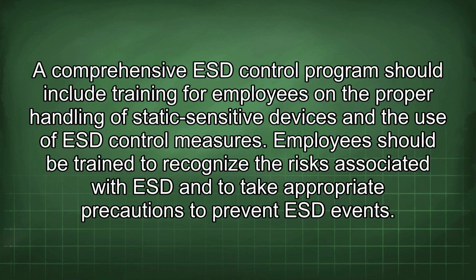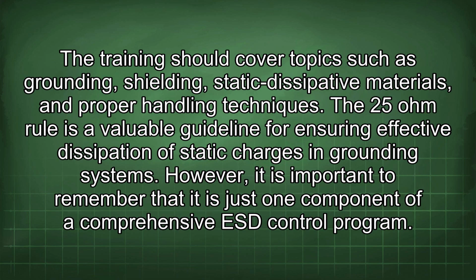A comprehensive ESD control program should include training for employees in the proper handling of static-sensitive devices and the use of ESD control measures. Employees should be trained to recognize the risks associated with ESD and to take appropriate precautions to prevent ESD events. The training should cover topics such as grounding, shielding, static dissipative materials, and proper handling techniques.